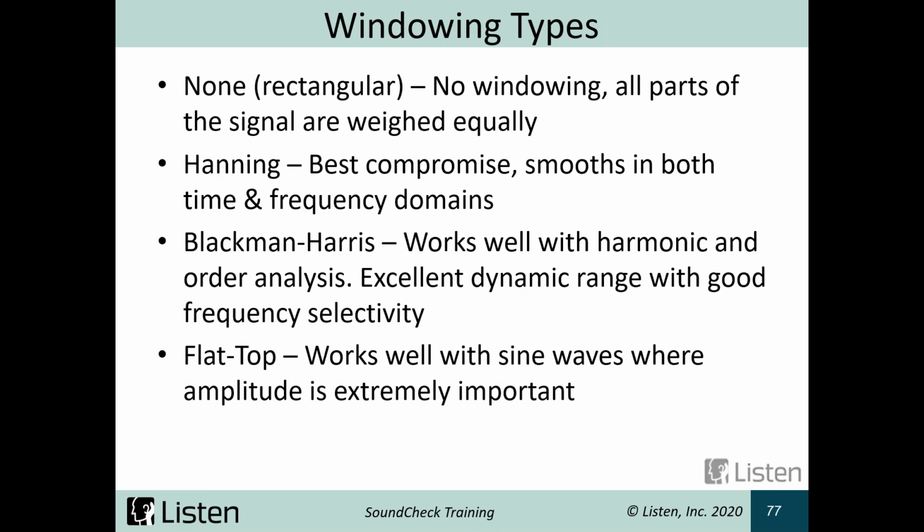Flat top is pretty close to rectangular. It works well with sine waves when what you really care about is the amplitude and you care less about the frequency domain. So in our microphone calibration, for example, we use flat top.